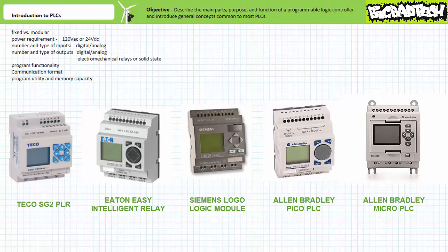These devices can be programmed via manual entry on a ridiculously small screen or via communications link in a PC running manufacturer-specific programming software. Some manufacturers offer fully functional programming software for free. Other manufacturers may require purchase of the programming software. The fully functional programming software allows a user to create and simulate a program, as well as download it to an actual device and sometimes monitor the process online.